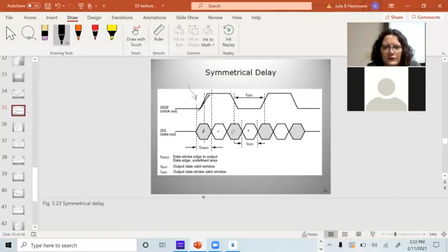But what these things do is, let's just say this is a slow clock. We'll call this 100 nanoseconds. If this is 100 nanoseconds, what the delay lock loop is going to do is it's going to produce a pulse that happens 25 nanoseconds after the clock edge to clock in the next bit of data. Another 25 nanoseconds later, it'll clock in the third bit, and then another 25 nanoseconds later, it's going to clock in the fourth bit.